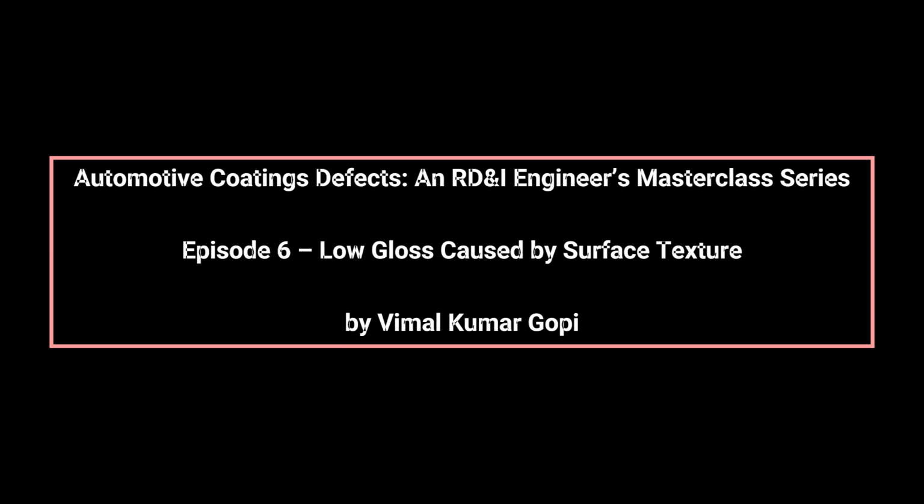Gloss approval in OEM environments is never based on gloss numbers alone. Visual assessment under controlled lighting remains critical because human vision integrates multiple optical cues, including distinctness of image, haze, and sparkle uniformity. A panel with acceptable gloss units may still be rejected if surface texture causes image distortion or inconsistent appearance across panels. Conversely, slightly lower gloss readings may be accepted if texture is uniform and visually pleasing. This reinforces the principle that gloss meters measure reflection intensity, not perceived quality.